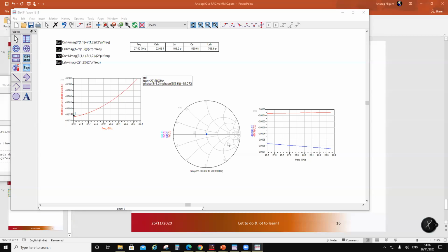My explanation is this: if you have used correct formulas, you will not see the mismatch. Because what did I do? I did an equivalent for a 50 ohm system, right? So all these equivalents are written for a 50 ohm system, right? So how can you have a mismatch? You will have mismatch because you use those formulas which somebody has derived. And in their derivation, they are tolerating over a bandwidth certain VSWR. Well, their formulas were wrong.